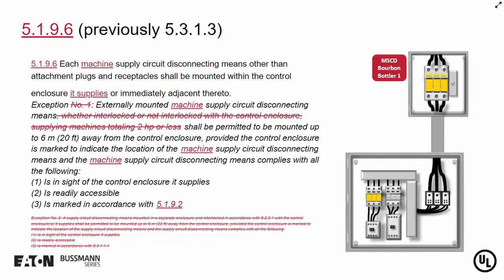One, it might be that when they turn off the disconnect for the primary main controller, everything in that bottom panel is de-energized. They also might have to go in there from a maintenance and troubleshooting standpoint where they have to have proper PPE. And by doing that, if they do have to defeat the mechanism to open that enclosure, if that's required per NFPA 79, they can defeat that and they can go in there, but they know how to dress because the protection is immediately upstream.